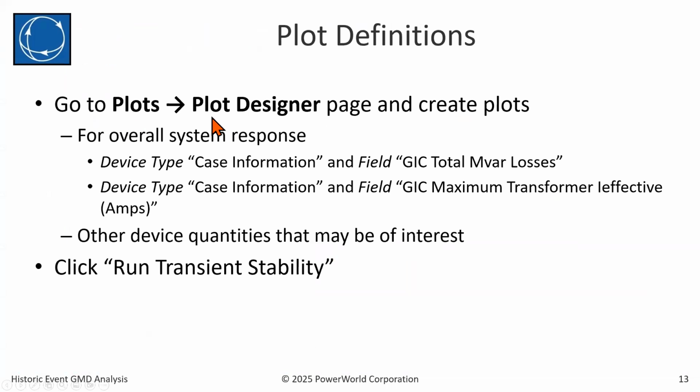Some of the things that you might want to do just to get a high level feel for the event and where the points of greatest stress on the system might be is to look at the total reactive power losses for the entire case. Or maybe if you're just concerned with a certain control area, if you are interested in your utility or maybe the ISO or the RTO that you're part of, you could have area or super area definitions that span that area of interest, and you could just make a plot for those, for example.